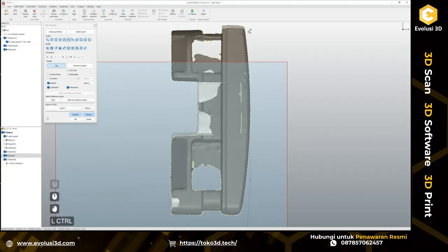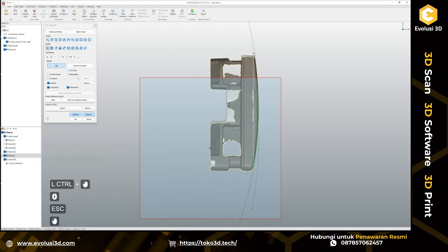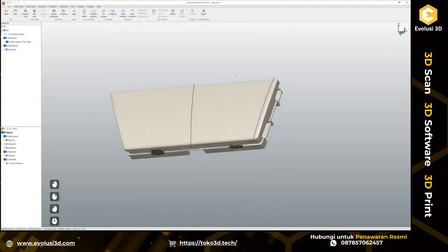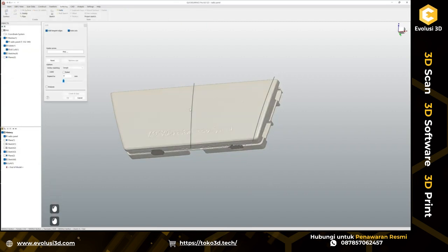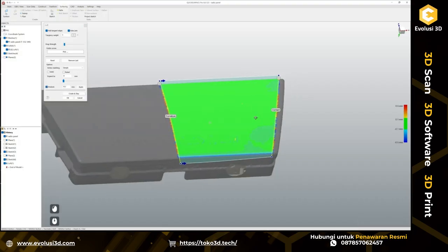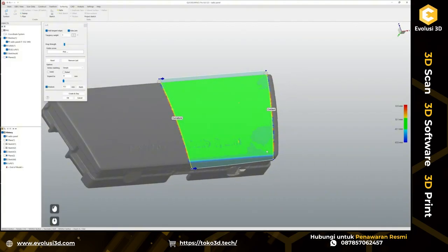Of course, here it might be a problem, and just a simple arc is not going to fit, but well, this angle is so tiny that it actually fits and works great here. So let's hide the plane. And what I want to do now is loft from this to this one. And here I will say this is tangent or even curvature. And we're just perfectly spot on.